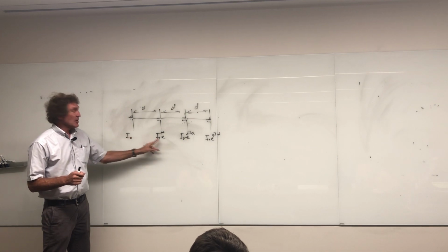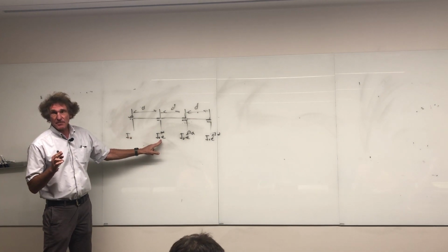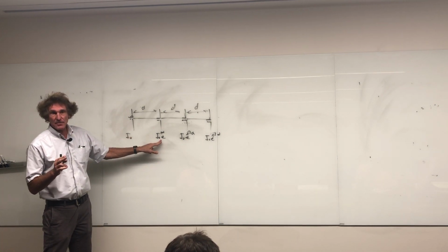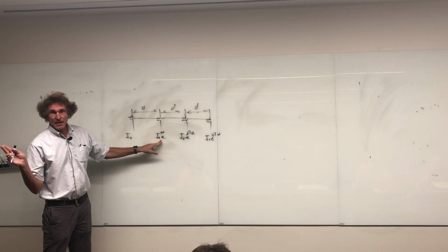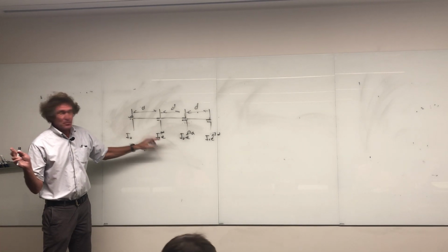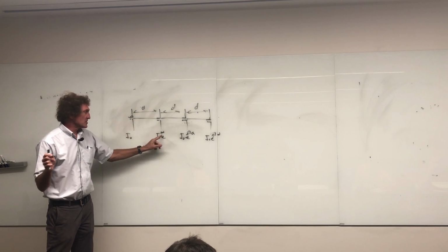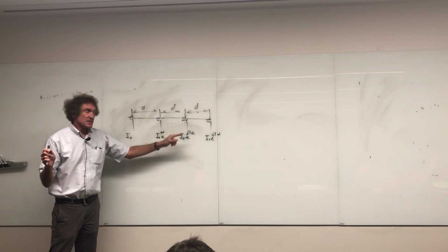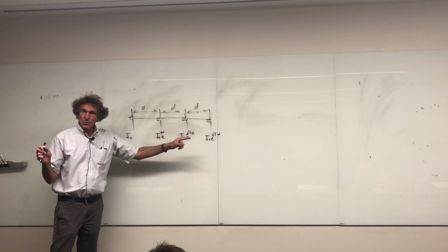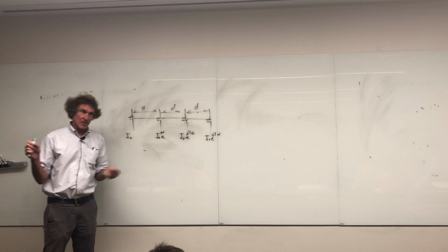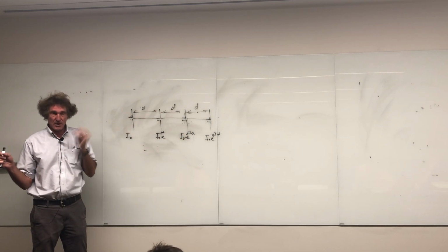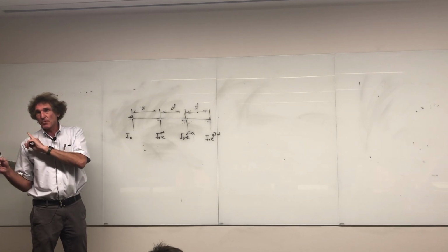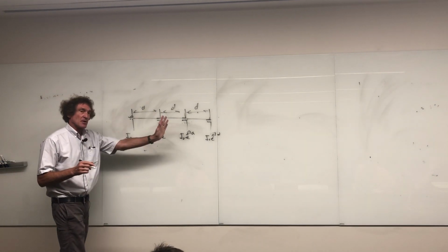So in order to get that constant current, they have something called a power coupler that we'll talk about later if we have time. Remember that. If you build an array and you put a voltage with just an increasing phase difference, like I'm showing here, you will not get the same current. You have to have a power coupler to cause that to happen. All right, that's important. But we're assuming we do, so we have these currents.